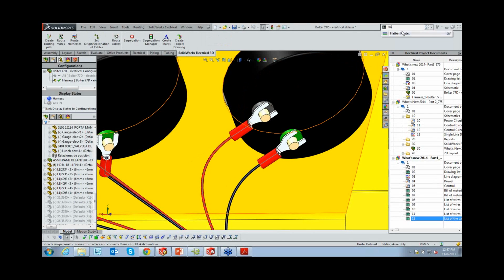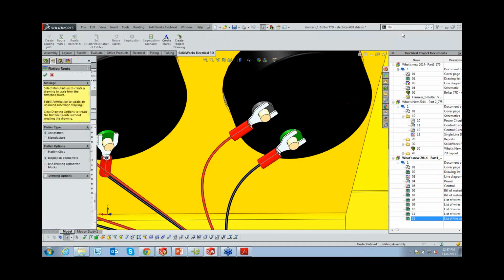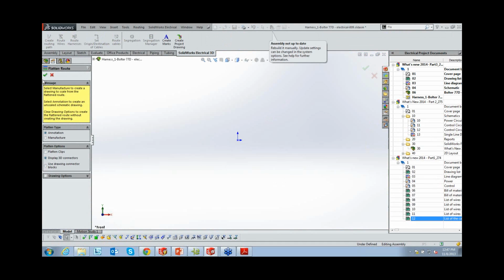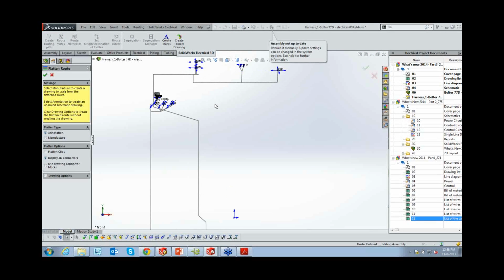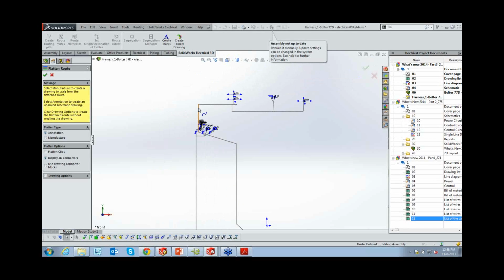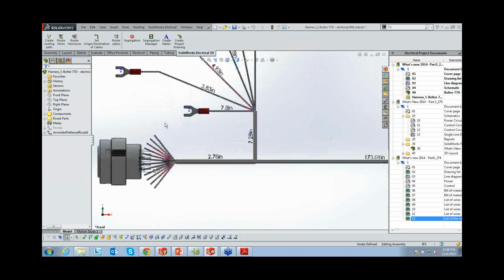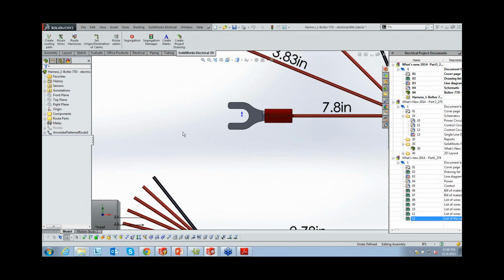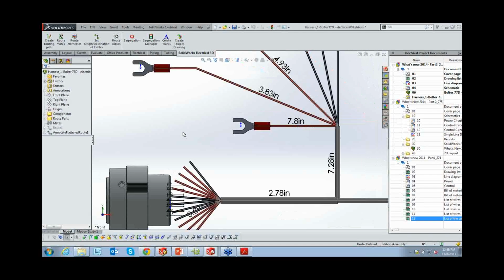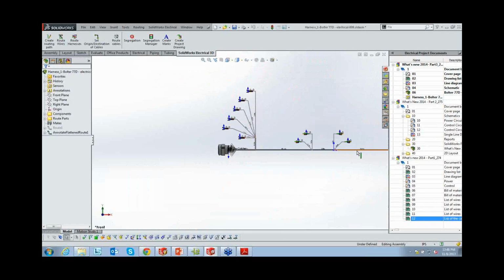Now, all this is really useful up to a certain point, but then you want to have that ability to flatten everything. So this is what the route looks like once everything is routed. You have all your connectors and components, and I'm simply going to let it flatten as an annotation. You can also do it by manufacturer. And you see how fast that did that? Wow, so let me follow this. You have a flattened harness with all the ends, with all the wires, all the length. The length information, the color, it's just a beautiful sight. It just does everything for you.